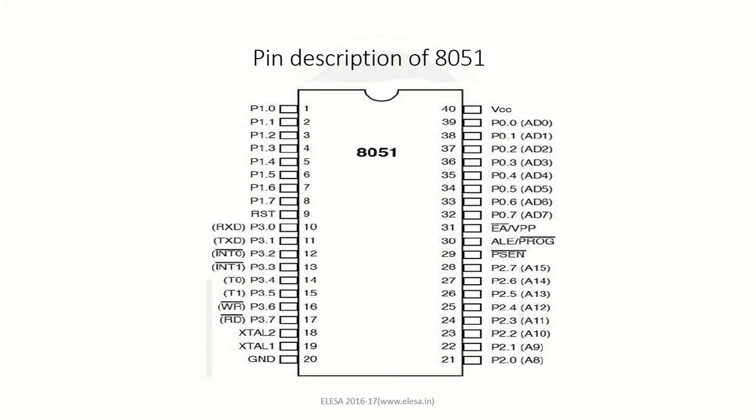Sometimes it can happen that we write a program in the 8051 and the program is huge and it exceeds the limit of the internal memory of the 8051. So we need to connect an external memory to the 8051. So whenever an external memory is used, these port pins work as higher order address bus. That is, it carries the MSB bit of the address of the external ROM. Therefore, they are named from A8 to A15, that is the MSB.